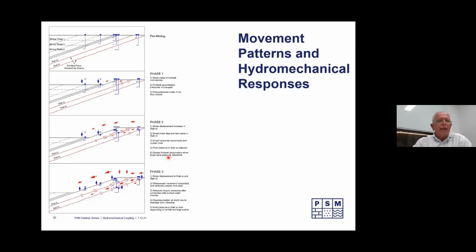This is a very good example because I'm going to show you what happens as we take off 3 layers of rock here in a layered strata. And these are little piezometers like we've seen before, little tubes, and the triangles are the starting water level near the surface. We take off the first layer and we get a reduction due to unloading. Remove the stress, the pore pressure goes down. No changes out here, even though we've got small movements, as shown by the red arrows.